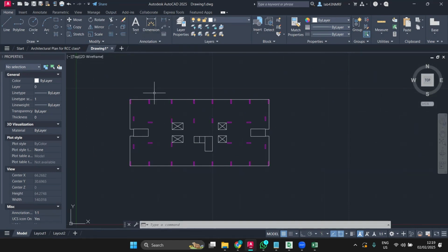Now there are some things you need to do in AutoCAD. You need to do purge. You need to remove unwanted layers, right? Whatever you want to do in CAD, freeze it. Try to fine tune it without having any errors and warnings from the CAD itself, because it's easy to rectify in CAD. You're getting my point.